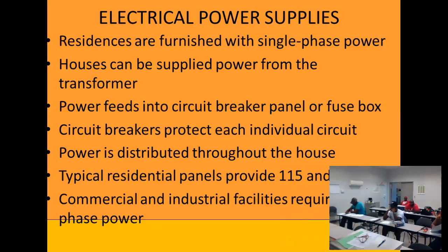A lot of the equipment we deal with, a technician will show up, yep, you got a bad contactor, you got a bad relay, and never wonder why. If it's 15 years old, fine. If a technician put it in there a year ago, maybe the voltage is wrong. Maybe we ought to take 5 seconds and check the voltage. That's what they're saying. To get the life out of this thing, we expect it needs to be within plus or minus 10%. We call it cumulative damage when it's running outside of that range. So that's our first rule that we want to deal with power, right?